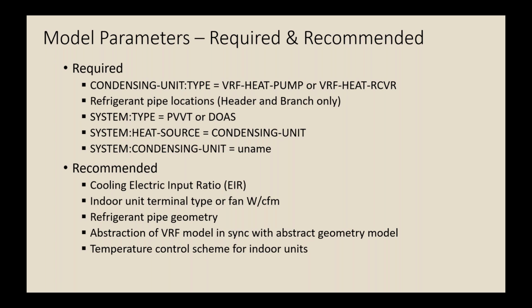You basically have to create a condensing unit, and you have to assign it a type. It's either a VRF heat pump, which means it is either serving units in cooling or in heating, but it doesn't actually allow the simultaneous heating and cooling of the system. Or you can have what the industry calls a VRF heat recovery type of system, and that one does allow simultaneous heating and cooling and recovering of energy from hot zones to cool zones, and it becomes a more efficient operation.